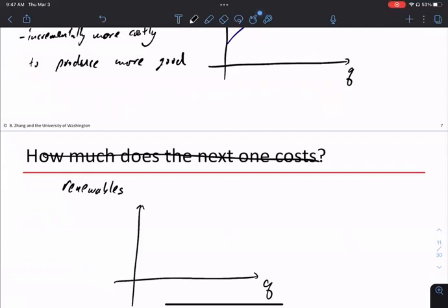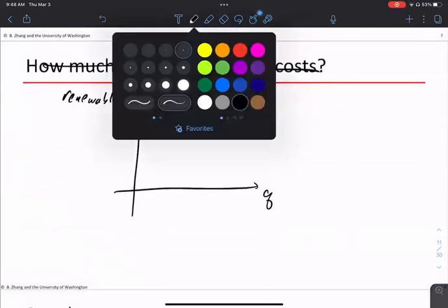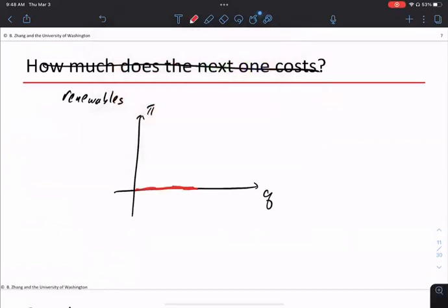That's what renewable is. Let's say you look at solar: I can generate 0 cost up to the solar irradiance I have on my panel. I cannot generate a single unit more after that, right? So it's 0 cost until a point, then infinity. Renewables have very, very weird shapes and curves. It's 0 up to some point, then there is infinity. Think of this as infinity. It's not possible to generate more here.